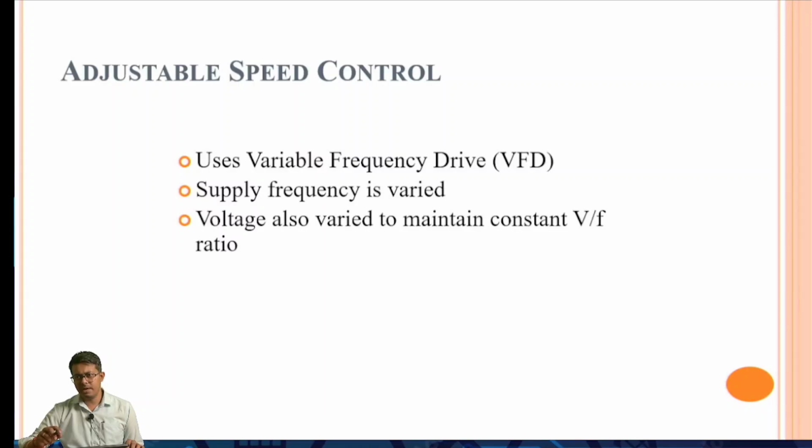Now in adjustable speed control, as we have designed different power electronics converters nowadays, we use these for variable frequency drives. Means by varying the frequency, we can control the speed. So according to the speed, we can use this synchronous motor for different types of applications.